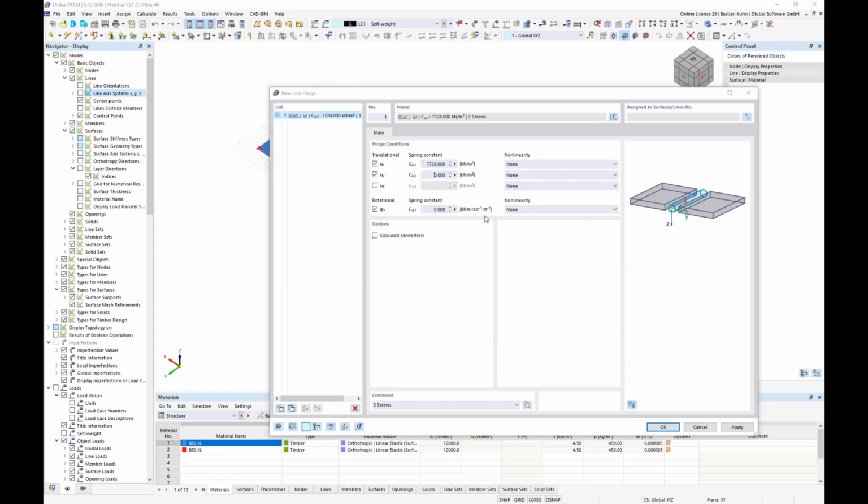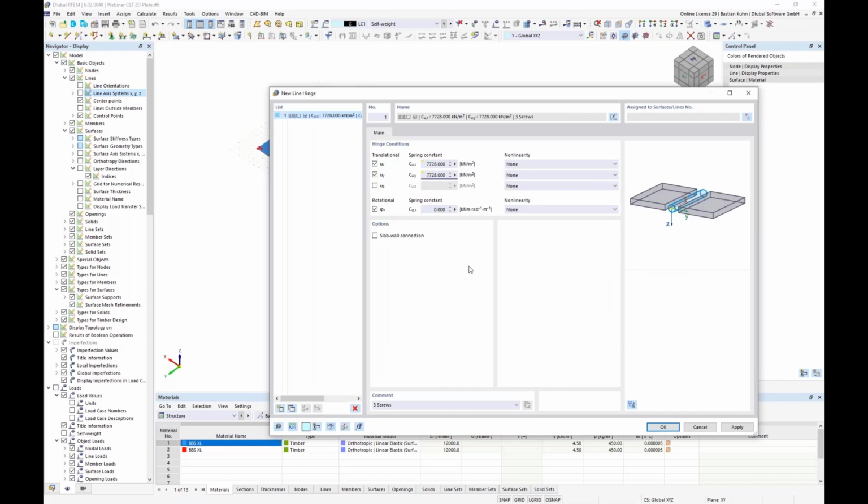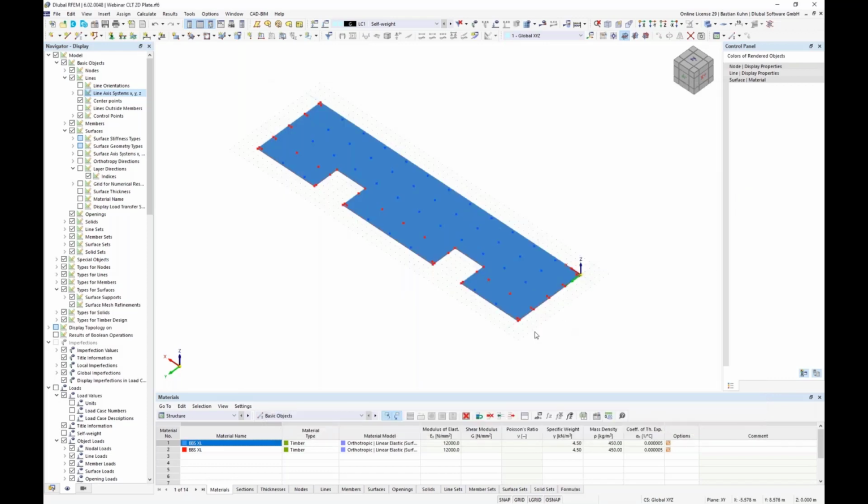Okay, so then second, we do it also for the Y direction, because according to the spring laws, you need to have it in the plate area for X and Y direction. Rotational spring constant, with newer researches, it is also possible to define a value in here, but right now I'm leaving 0. Of course, you could have something similar, like I did for X and Y direction, also for the rotation. And in that direction it is not necessary to define any kind of slip.